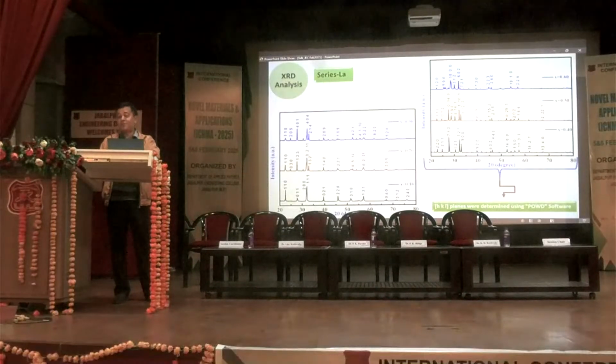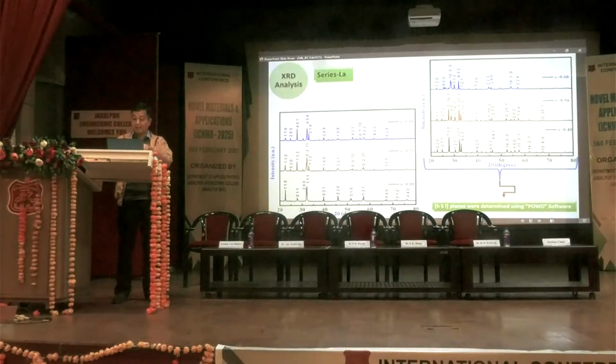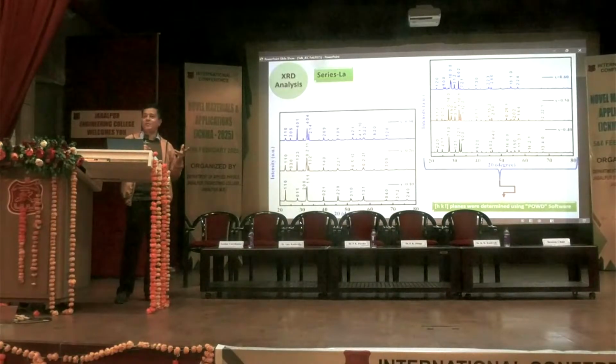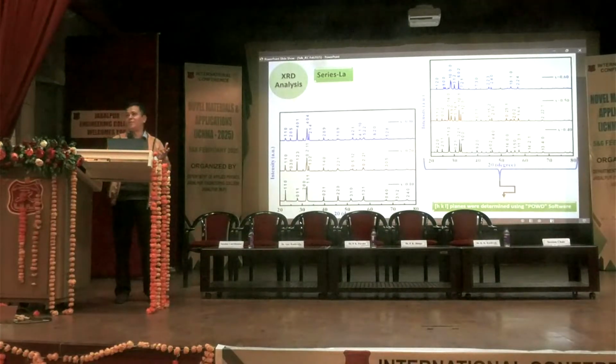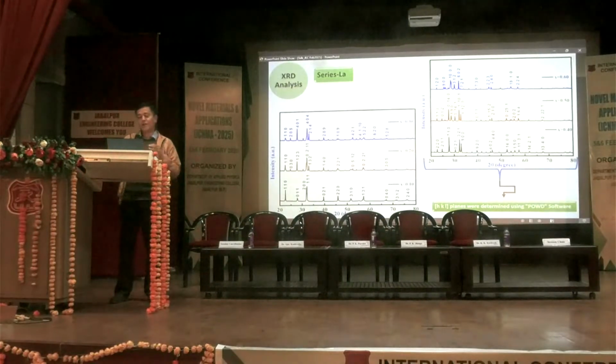So these 220 and 110 are the HKL values corresponding to that peak. But still, some impurity may also be there because of the casualness during the preparation. You cannot always keep the ideal atmosphere, so some impurities will be there. Then you can highlight those impurities in the peak during your analysis also.